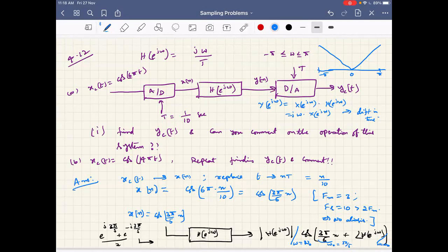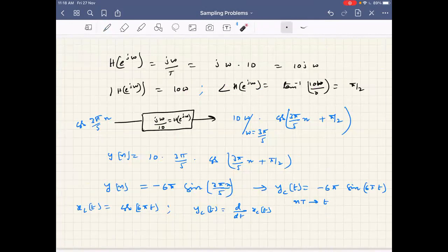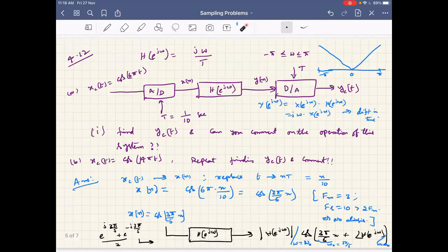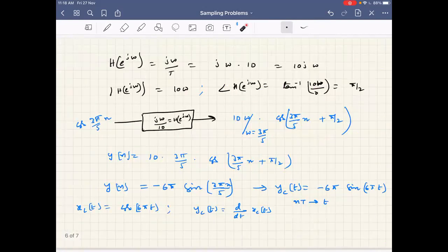Differentiation means wherever the change happens, you are highlighting it. In the time domain, if there is any change or variation happening across the signal, you are highlighting that. Say minus 10 to plus 10, you get 20 as the value of differentiation. If it is 10 and 10, the differentiation is zero, no variation, smooth. So you are identifying and highlighting the variations, which is exactly the operation of a high pass filter. High frequency variations are enhanced, and the smooth parts with no variations are suppressed. Okay, fine.